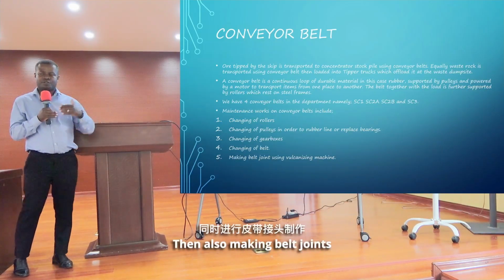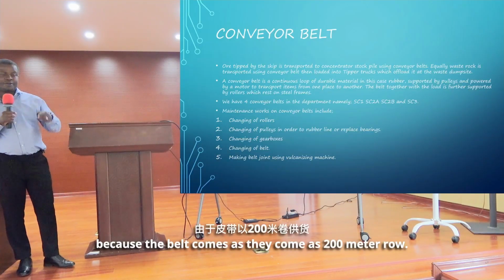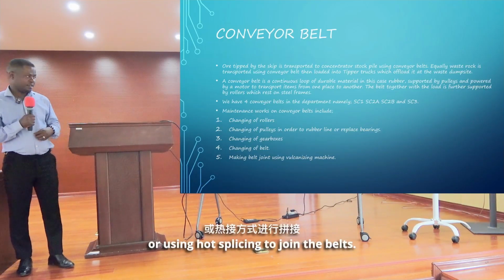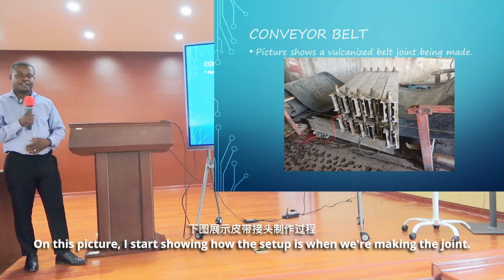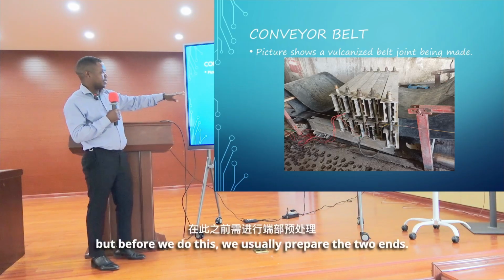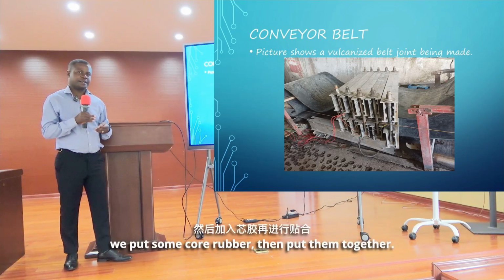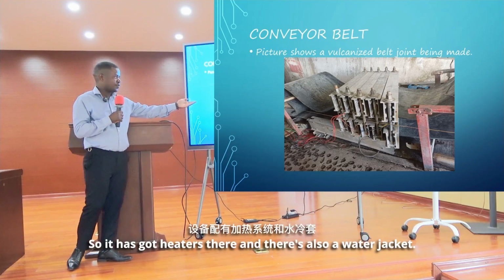Then also making belt joints, because the belts come as 200-meter rolls. Those belts, we were using hot vulcanizing or hot splicing to join them. This picture shows how the setup is when we're making the joint. We've got clamps there, we've clamped the joint, but before we do this, we usually prepare the 2 ends. After preparing the 2 ends of the belt, we put some core rubber, then put them together. It has got heaters there, and there's also a water jacket.